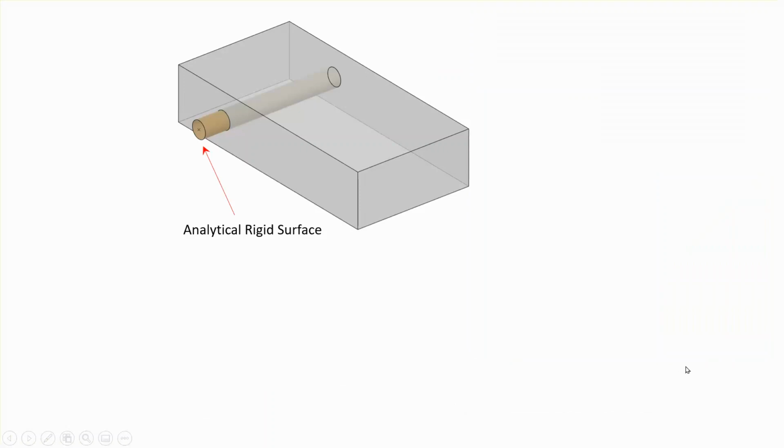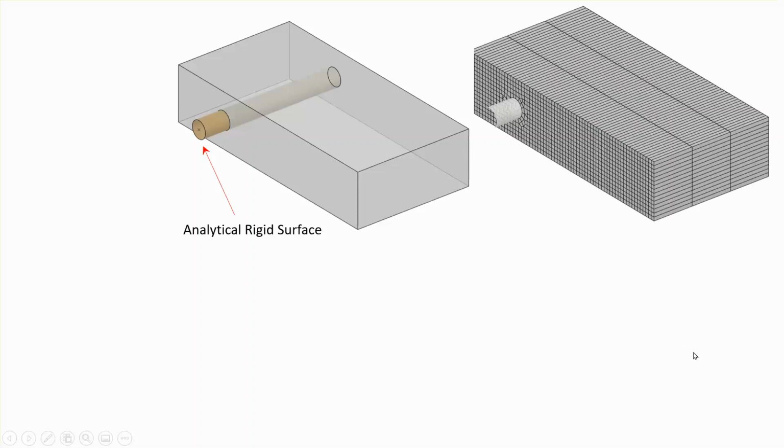So what I decided to do instead is, first of all, model the entire thing as 3D. However, I'm modeling only half of this plate, actually a quarter of the plate, because there's a plane of symmetry at the bottom of this block, and there's a plane of symmetry at the right side. Okay, so basically this is 1/8 of that geometry that you saw, and I've meshed it like that, so it's rather fine in the lateral direction. But I didn't want to take a long time, so I made it only three elements through the depth here.